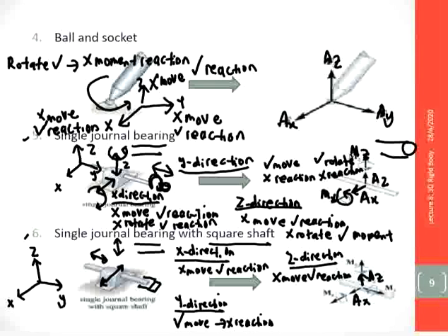For the x direction, can this long shaft rotate about the x-axis? Cannot rotate. So there is a moment here. Moment reaction Mx.